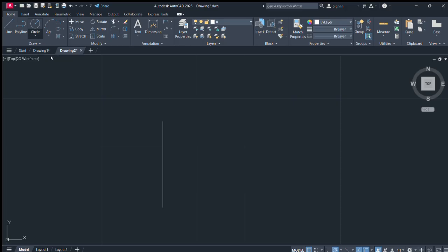Then next up, we're going to draw the circles that are at the tip of the line. From the center point of the line, which is at the top, we're going to draw our first circle by going to the circle center, diameter option, and we enter a diameter of 3.6. Next up, we go back again to the center diameter circle and draw a circle of 4.8 units.